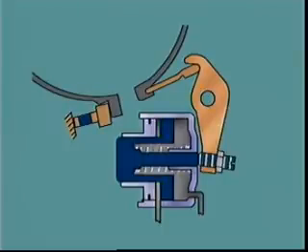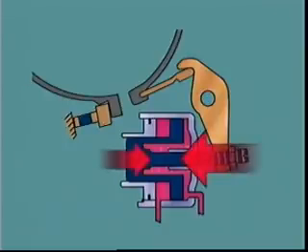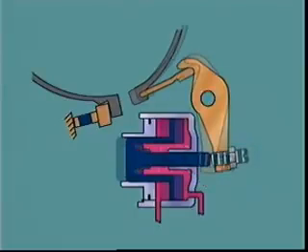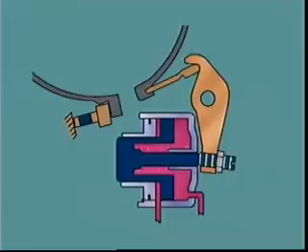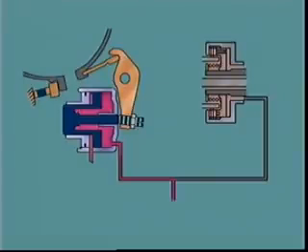The band is brought into operation by directing fluid onto the reduced area that surrounds the hollow portion, accommodating the return spring. When fluid at the same pressure is directed to the release side, the differential area results in a higher release force. The band can be released even while apply fluid continues to exert force on the piston. The fluid directed to the release side can be directed at the same time to a clutch piston to bring the next component into operation.